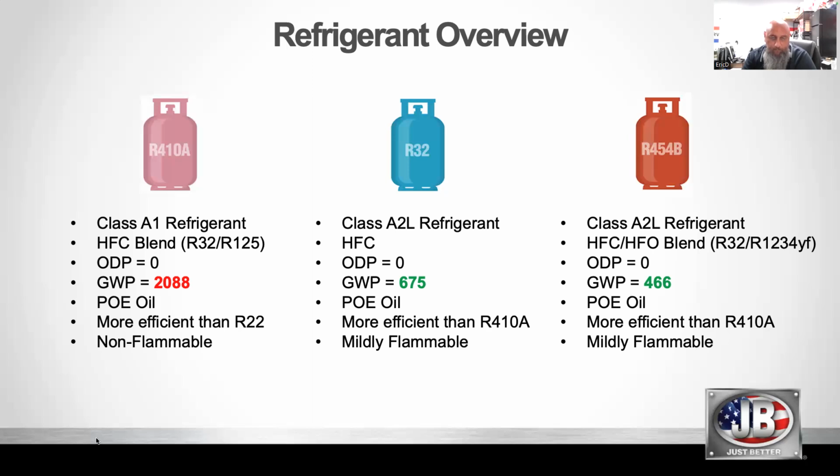No other changes with the POE oils, and the charge sizes are slightly smaller than 410A. In the case of R454B, the pressures are pretty similar to 410A, so that transition shouldn't be too much of a problem if you can take the flammability side out of it.